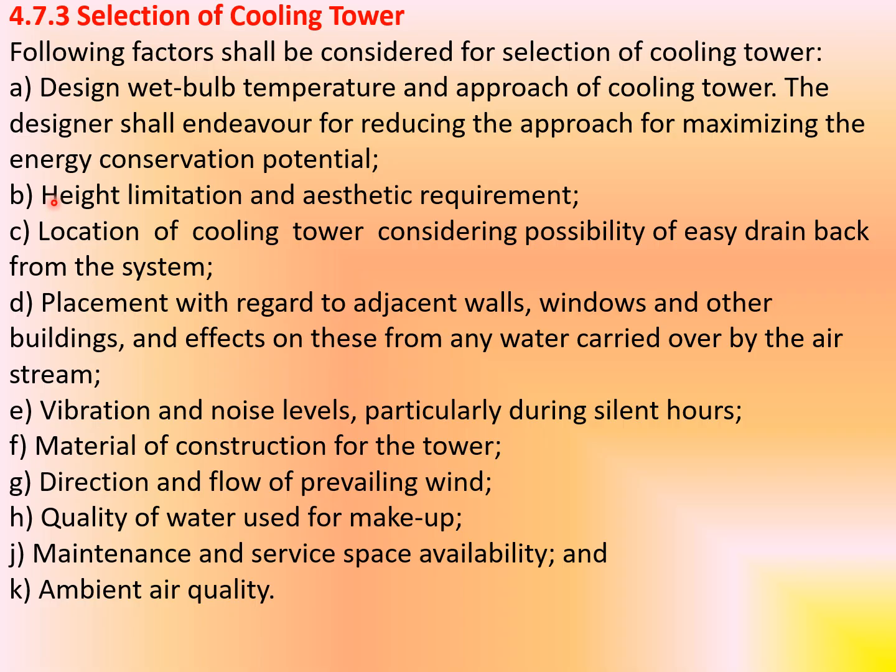B. Height limitation and aesthetic requirement. C. Location of cooling tower considering possibility of easy drain back from the system. D. Placement with regard to adjacent walls, windows, and other buildings, and effect on these from any water carried over by the air stream. Next, vibration and noise level, particularly during silent hours, that means in night.